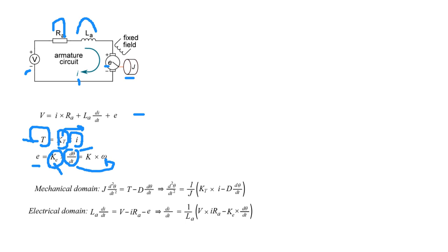Now, if you see, J depends on the torque value, and B, what is B? B is the viscous friction. Okay. If you want to model your mechanical side, maybe you can remember 1 over Js plus B. You modeled it last week.